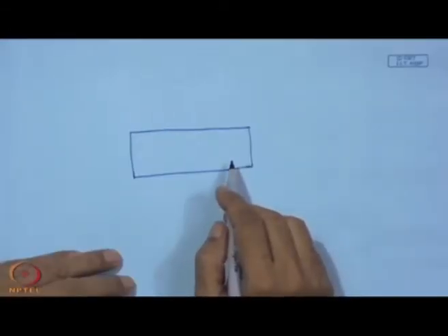Now, this surface has to be activated or passivated. We know that for diamond, the surface is not ordinarily active, so there are a lot of steps before one can start the CVD. That means substrate preparation becomes one of the important steps before conducting CVD. So, we have two choices, either activation of the surface or passivation of the surface.